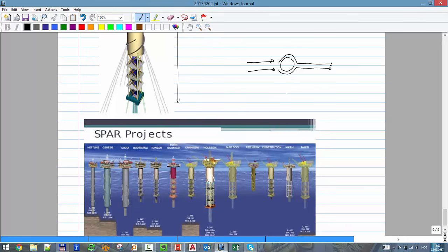What happens is that you have some turbulence, and the flow breaks loose before that middle point. This phenomenon is also not steady; sometimes it oscillates up and down. This point where it detaches, the detachment point, goes up and down. It oscillates.